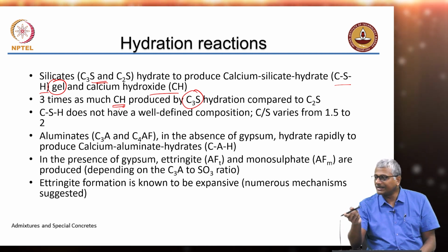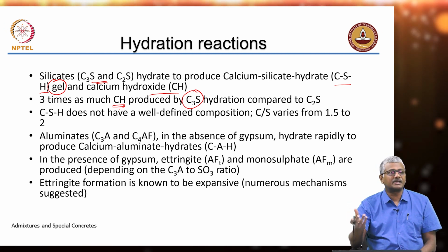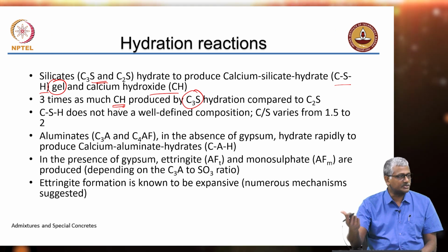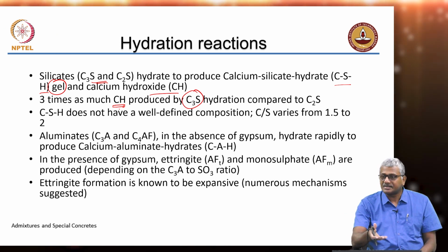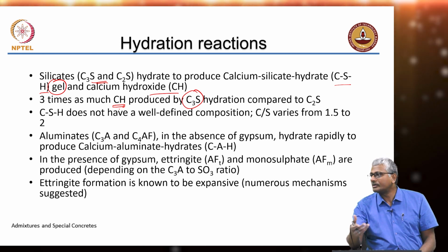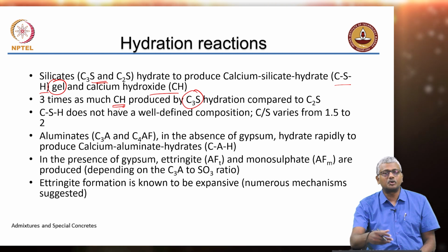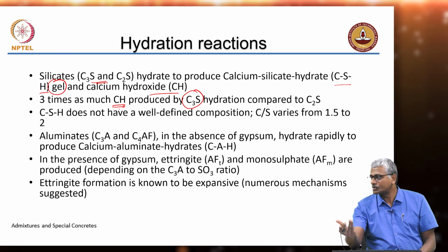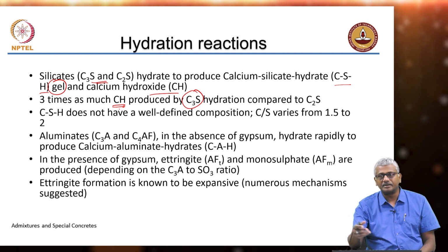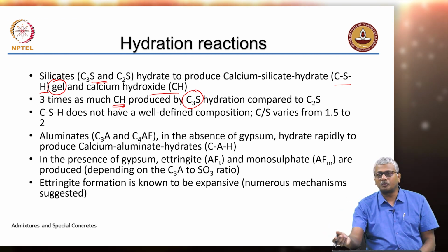We talked earlier that a pozzolan has reactive silica and this silica combines with calcium hydroxide to produce CSH. So, in a high C3S system, your possibility of pozzolanic reaction is going to be more: more C3S, more calcium hydroxide, more available lime for pozzolanic reaction.